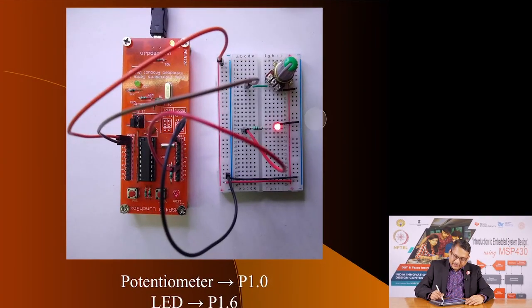And so what you should see when you compile and load this code into your lunchbox. Let me correct myself here. The LED is connected to P1.6, which, as you recall in our previous exercise, is not the onboard LED. The onboard LED is on a different pin, a pin which does not have a PWM function. We have connected the LED to P1.6, which is connected here.